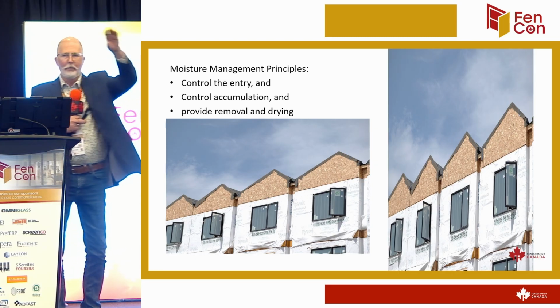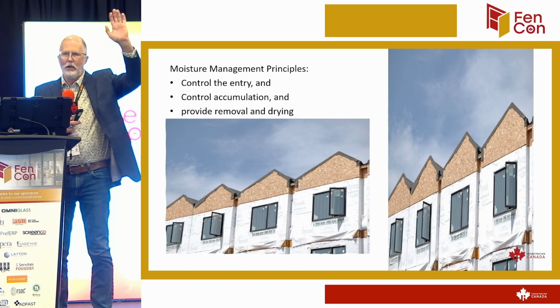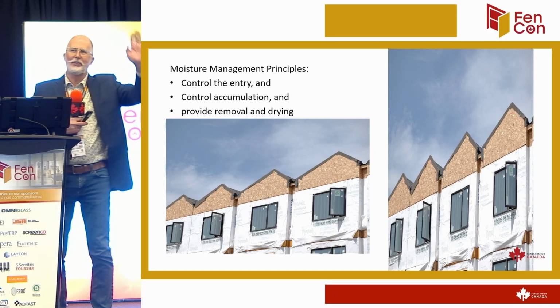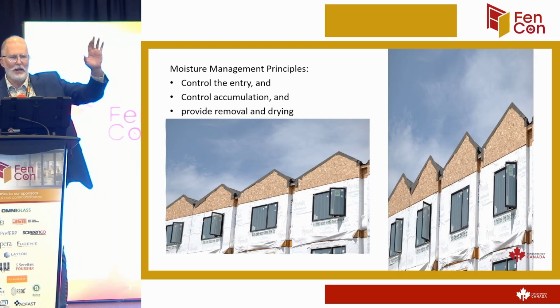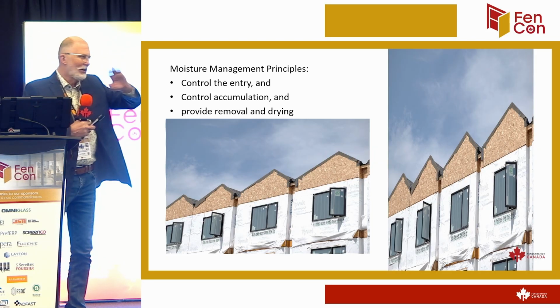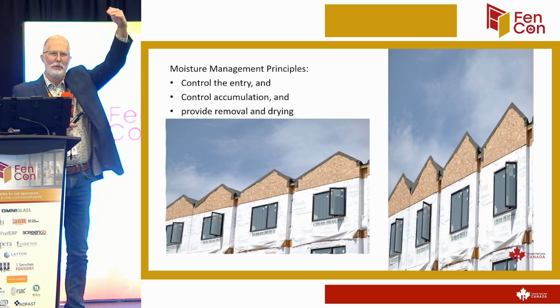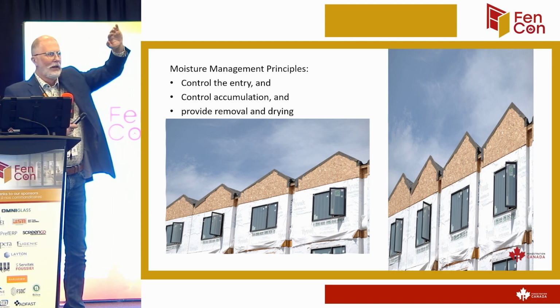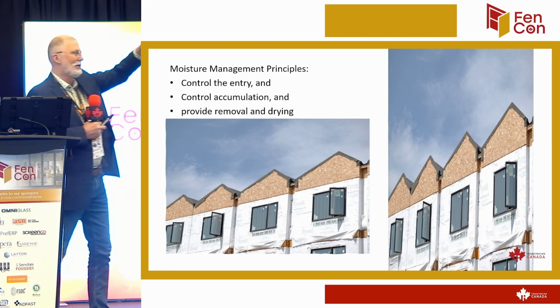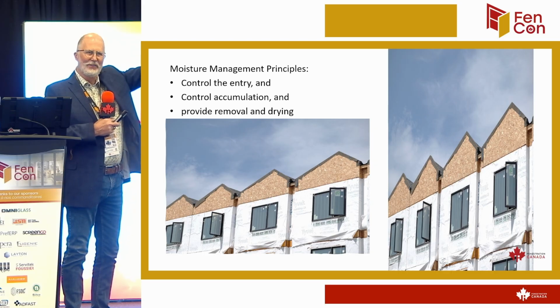But they did put a peel and stick on the roof, which folded over to the face, which is nicely stapled on the face. So typically, what should happen here? The next guy coming along should continue that paper upwards. He should lift that peel and stick up and tuck his paper underneath it and pull it down. Well, how many times is, well, it's not my job. And it goes over, so now the water's on the inside.